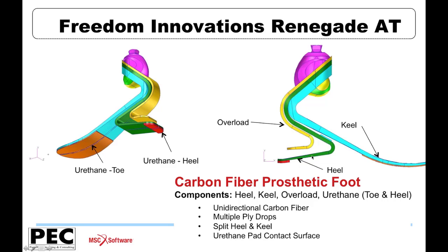The other component that we'll focus on primarily in the analyses that I'm presenting today is the one shown in green here, the heel component. And that's back at the back, as you might guess. And this particular design has what's referred to as an overload component. Basically, it's a travel limiter, and to try to prevent overload of the heel, so to provide contact and an additional amount of stiffness and restraint against excessive deformation of the heel.